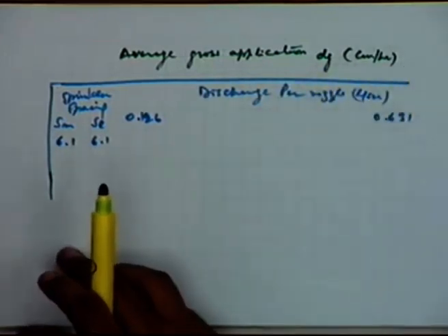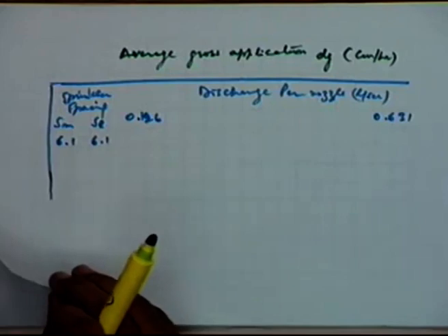You can make the selection directly, how much average gross application you are getting under those circumstances when you select a particular nozzle. So there are many such aids which have been provided for making the designer's effort quite minimal, and the designs can be taken up quite quickly.